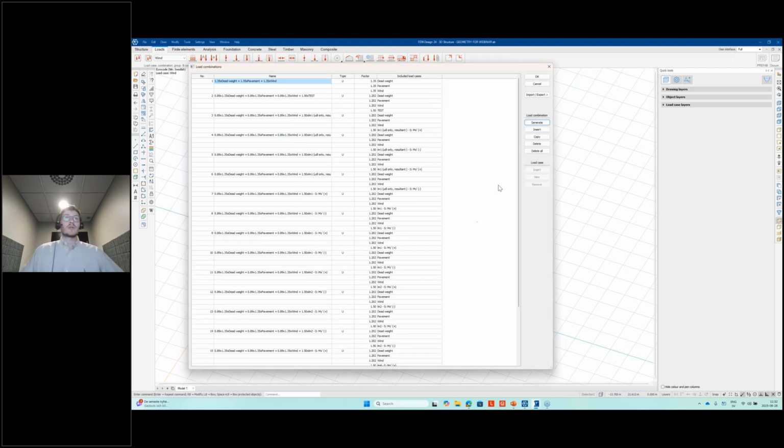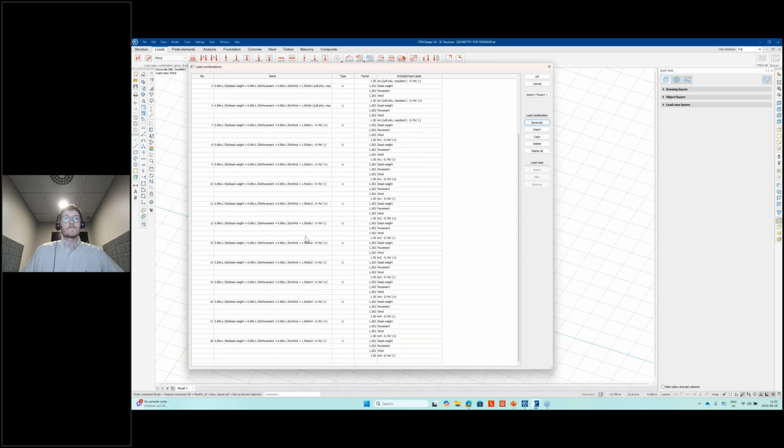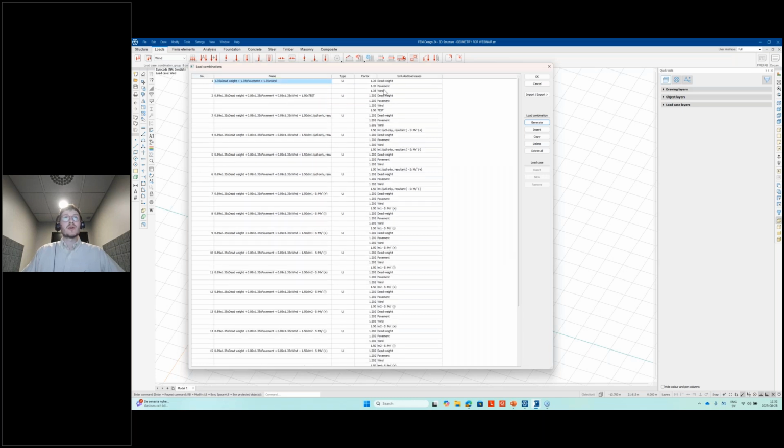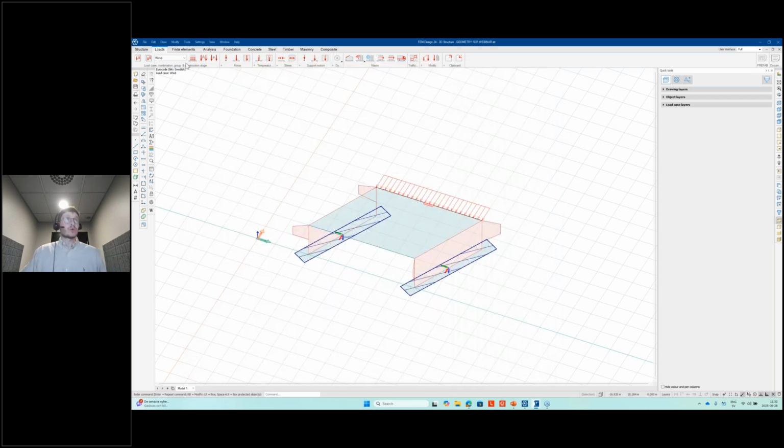get all of these load cases. And again, we can see that dead weight plus pavement is included in every option. I guess the wind also, since we only have the wind load in the variable loads, but otherwise this would change, of course. And then we have one load case for each different traffic load pattern and result that we requested. So this seems fine. Let's go to the separation.